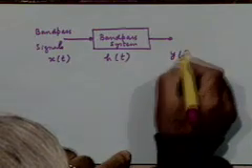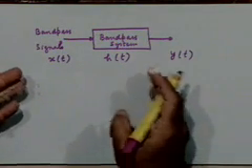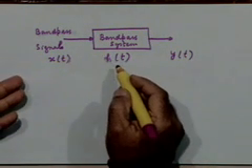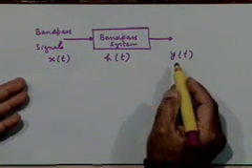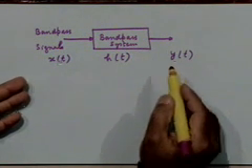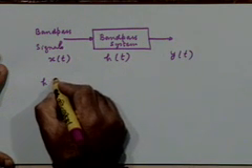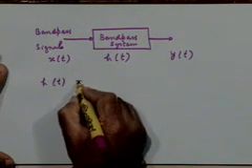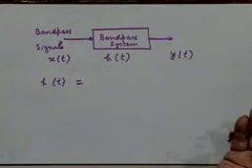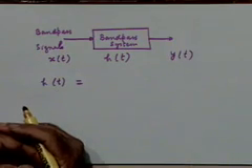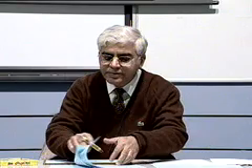And let's say the output is y of t. I know how to deal with systems, so you say what is the big deal? If I know h of t and x of t, I can find y of t by convolving x of t with h of t. But what I am saying here is, I know that both h of t and x of t are essentially bandpass in nature, so they will have this quadrature representation, or the complex envelope representation, that we just discussed. Incidentally, I probably forgot to mention something about this representation.